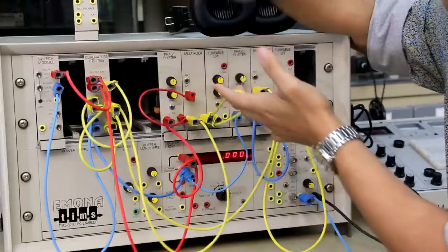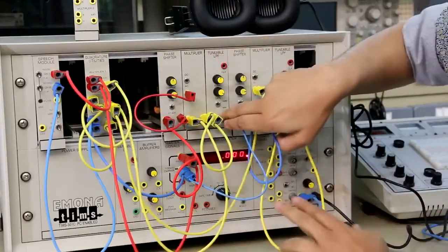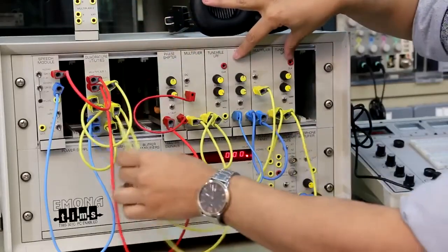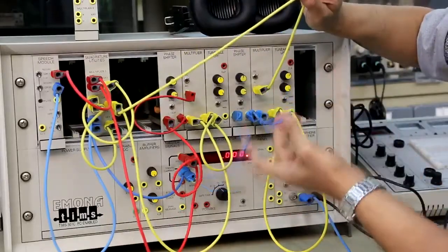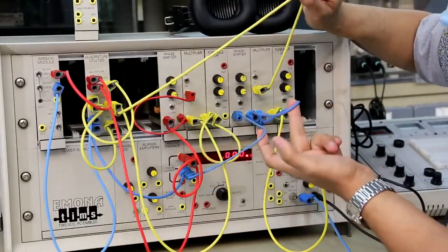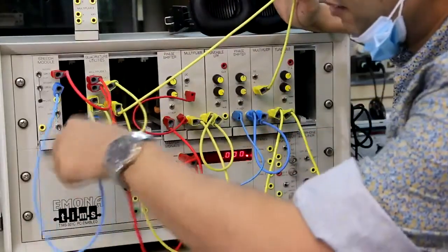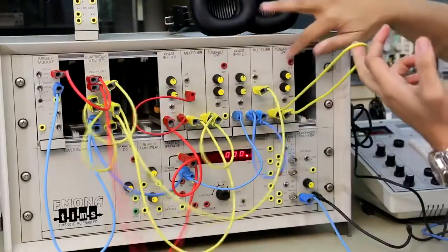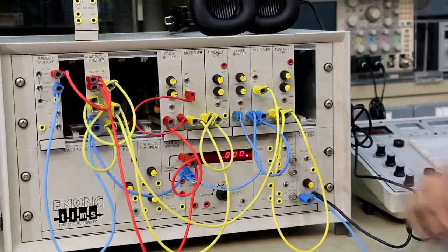And then that signal goes through a low pass filter, and this is my message 1. Same thing happens for message 2. The QAM signal is multiplied with a phase shifted cosine signal, because on the modulator side I'm multiplying with cosine, and then that is passed through a low pass filter. So let's listen to it now.